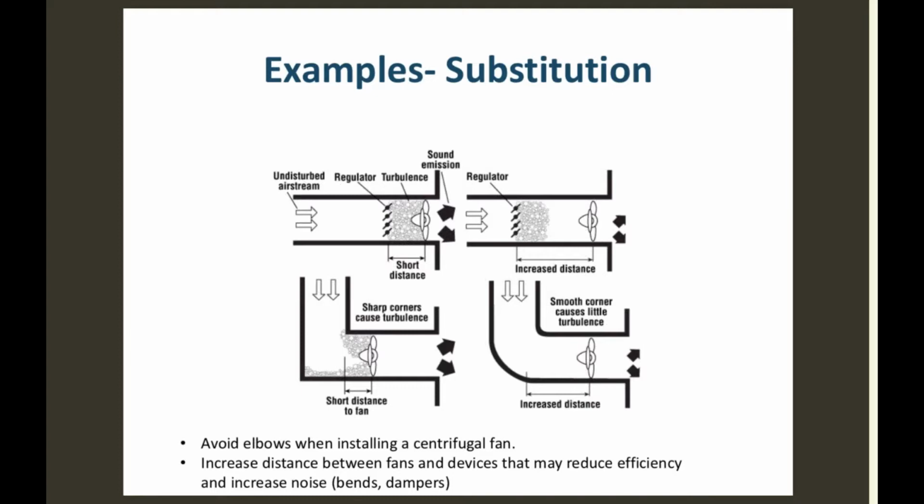Now, it could be somebody left them wide open. It could be that they're motorized dampers or pneumatic dampers, connected to the thermostat back there, and the controls, that's called a variable air volume system. And those controls should control how open those dampers are. So if the room gets warm and we get more cold air, they open a little more, but not wide open, right? So it could be the controls are bad, could be the dampers are jammed, could be a number of reasons, but the reason for the noise was the velocity was too great.